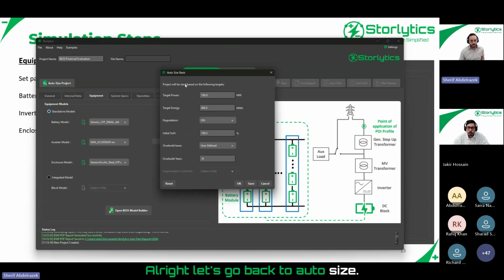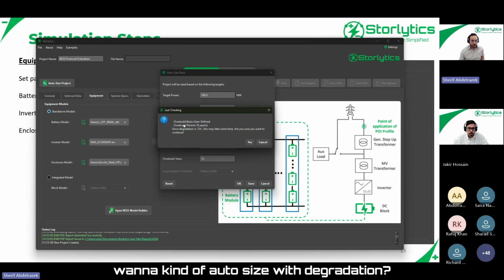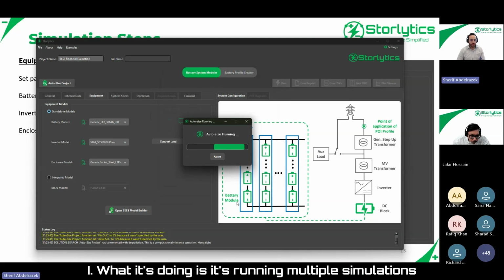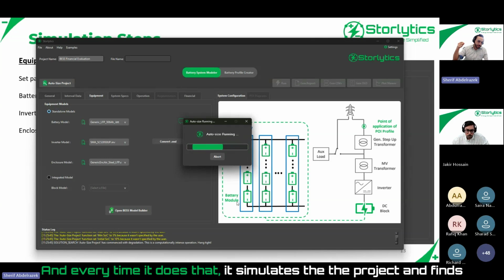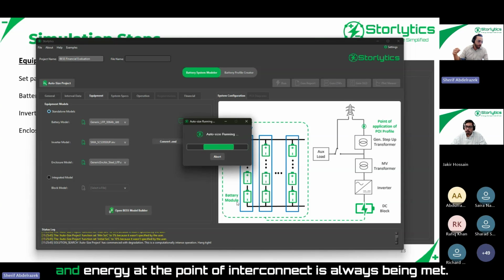All right, let's go back to auto size. So we went over these items here. We can then click OK. Then it'll tell us, all right, are you sure you want to auto size with degradation? This may take a little bit of time. So here we'll click Yes. And what it's doing is it's running multiple simulations on the back end, trying out different project sizing, going from small energy capacity to larger. And every time it does that, it simulates the project and finds the degradation, and is trying to make sure that your target power and energy at the point of interconnect is always being met.